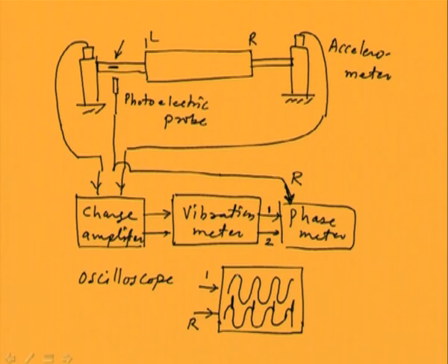The phase measurement can be like this: at the maximum of the signal, this time duration can be noted, and we know the time period T of the signal also. T corresponds to 360 degrees, so small t1 can be converted to the corresponding angle.